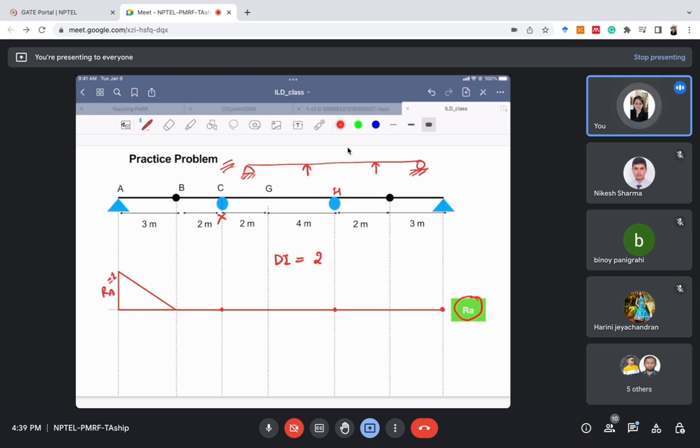By adding the internal hinges, we are removing or balancing out the restraints. So I have added this restraint at B, and another restraint here at I. So I have added two more restraints. I've removed those, and now the degree of static indeterminacy is 0 in this case again. This is a quick method to determine the degree of static indeterminacy. I hope you have studied it, or maybe I'll cover it in coming lectures also. This is the quickest method by which you can determine it.